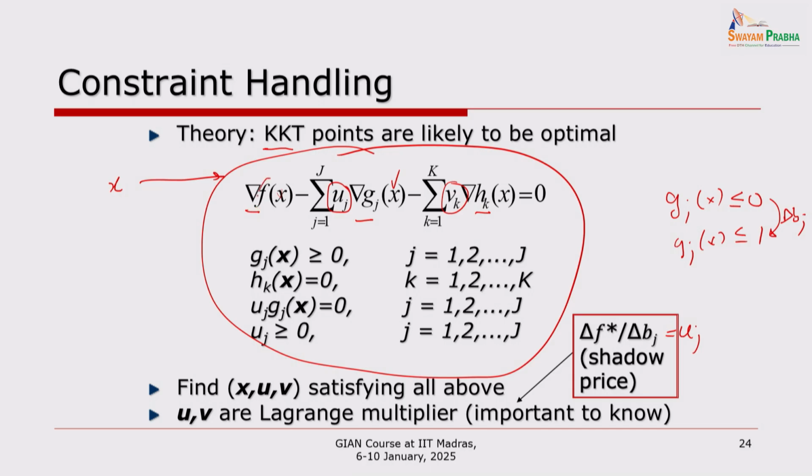So this could be my cost and g could be my, let's say, volume constraint. Let's say I'm designing a can with volume inside, I want a certain V, V greater than or equal to, let's say, 300 milliliters, and I minimize the total surface area. I have two variables, diameter D and height H. So I can find an f star, I can find the area, let's say A star.